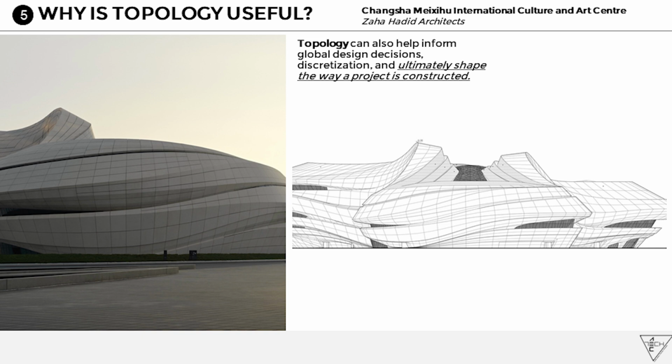And of course, one of the biggest questions is going to be, how do you control panel sizing, so that you don't have a billion unique panels? Well, that's also why we have the ability to use Grasshopper and all these computational solutions, because even though we can design freely, we can also look at the idea of constraining edges. If we understand how the object is constructed, we can take any individual edge and start constraining it in some way where it's a fixed edge length. And then those edge lengths can be rationalized so that we have some number of repeating panels versus a massive collection of unique panels, which obviously we do not want.